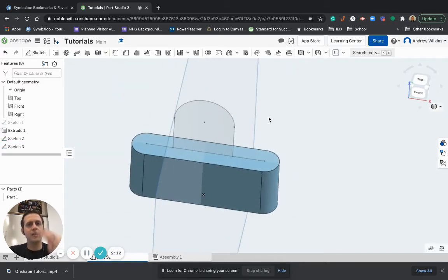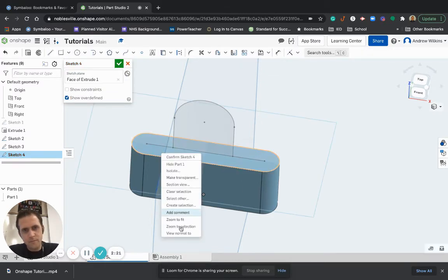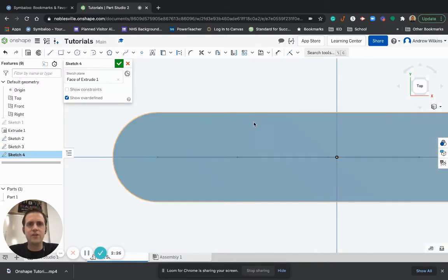Now, I can't do a sweep yet because that loop doesn't have a sketch of anything that I can sweep. So now I'm going to sketch on that plane right there. Because I chose this plane, if I go to do a line tool, it will lock into here because I'm literally using the top of this object. So that's why when you use a plane from an object, it'll do that.